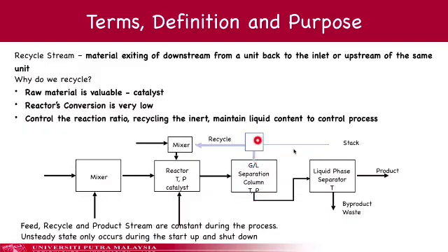The gas phase is recycled back into the reactor and the product stream is sent to another unit for product purification. The gas phase which is recycled, you can see here, is being split into two streams, which are a recycle stream and a purge stream. The purge stream, which is the waste from this system, is treated in a stack before being emitted to the atmosphere.